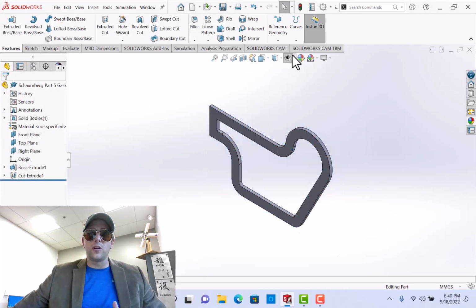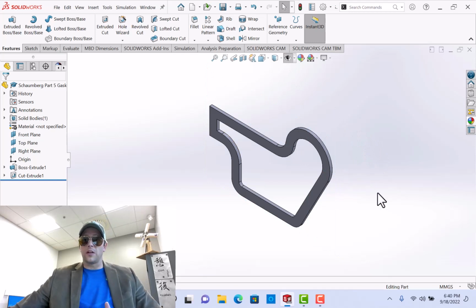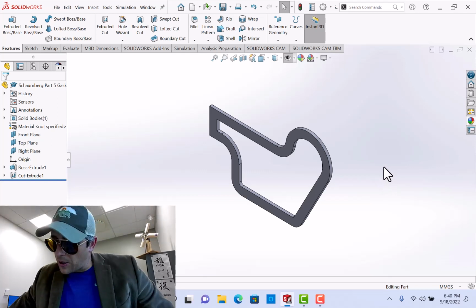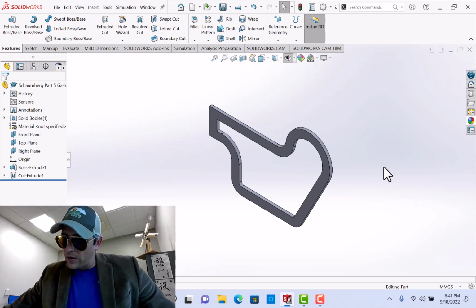Okay, so if I turn off the junk, that gives us a better view of what that looks like, and that's actually a pretty good thing. Now, for the offset geometry associated with the original geometry, on your own, adjust the height and design to 115 meters, and instead of the 120 vertical, change it to 105.